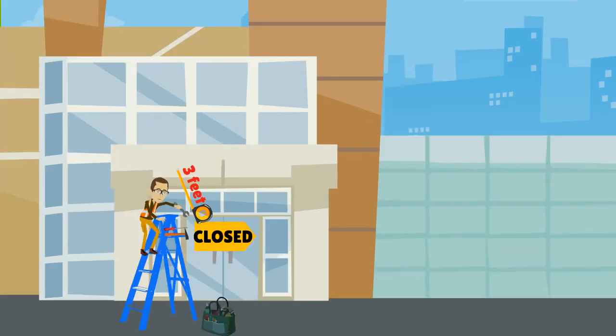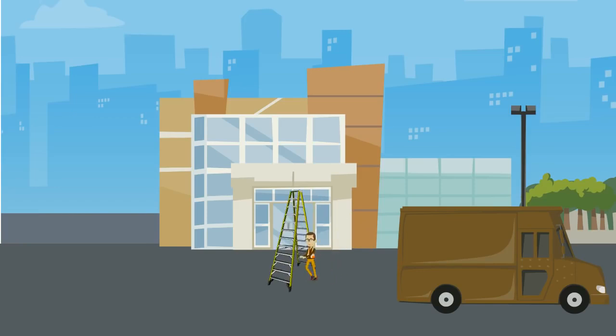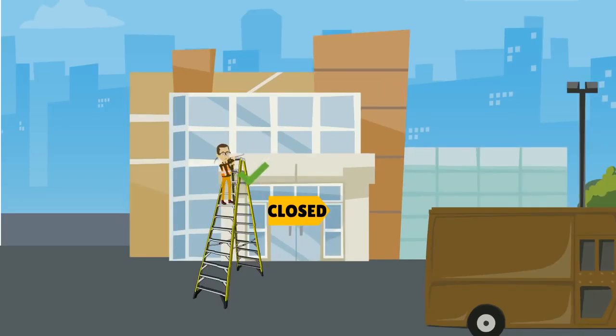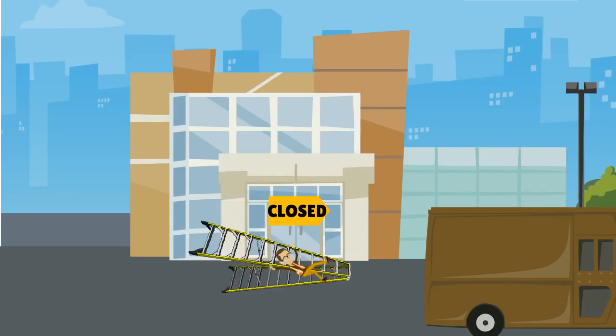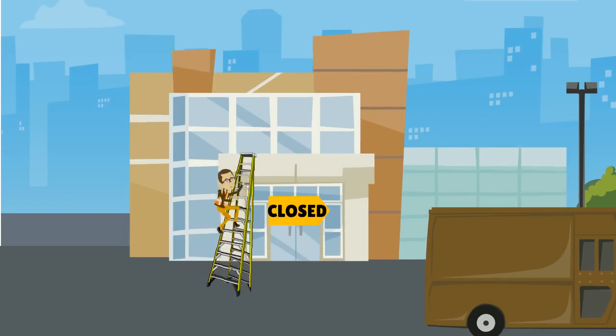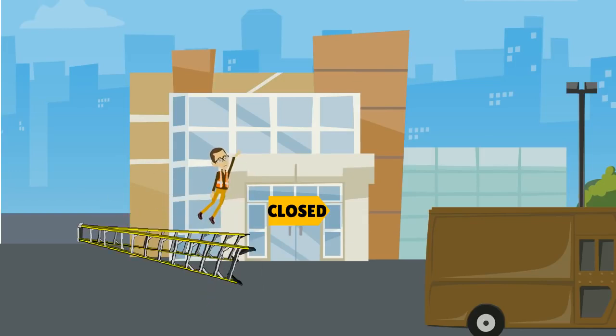Use a stepladder that is about 1 meter or 3 feet shorter than the highest point you have to reach. This gives you a wider, more stable base and places the shelf at a convenient working height. Place a stepladder at right angles to the work, with either the front or back of the steps facing the work. When working from a stepladder, keep your hips within the two vertical rails. Reaching too far to the left or right could cause the ladder to topple. Never lean a closed stepladder against a wall and then climb it, because it can easily slide out from under you.